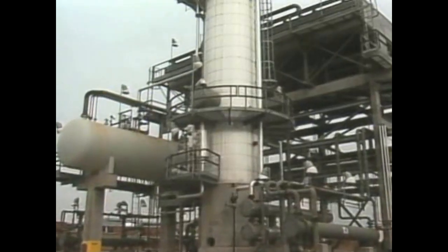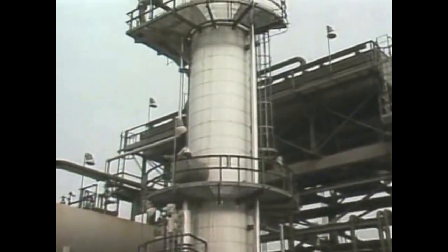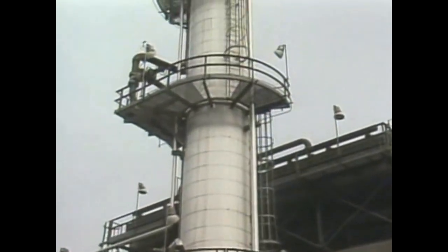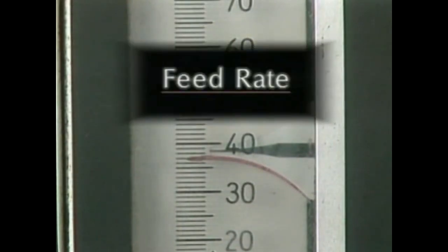Operating a distillation system involves maintaining an equilibrium or balance between the rising vapor and the falling liquid in the column. One aspect of operation that can affect this balance is the system's feed rate. The feed rate is the rate at which feed mixture is pumped to a column. The flow of feed to a column can affect the quantity and quality of overhead product and bottoms product.